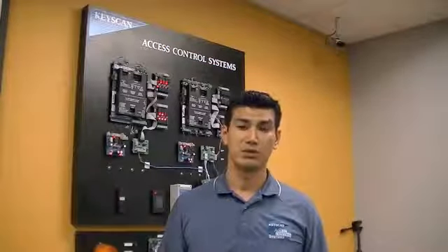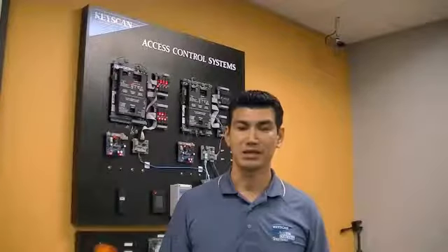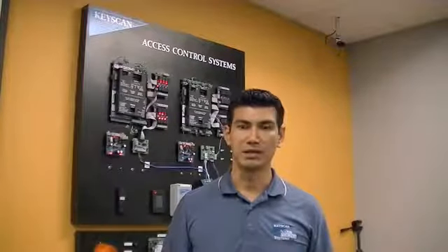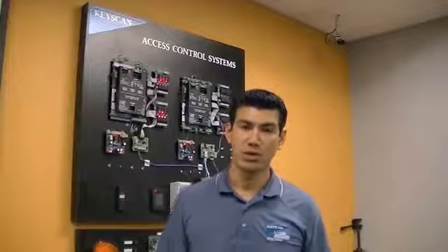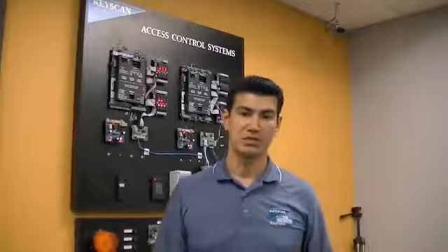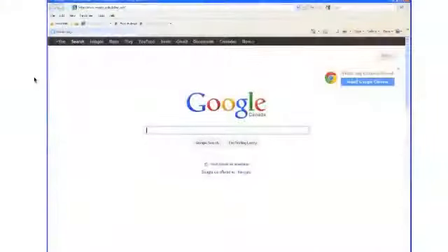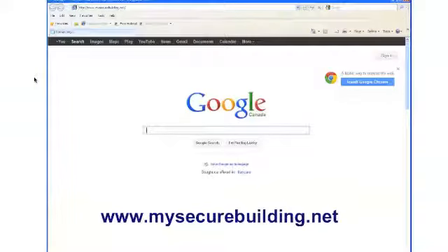Today we're going to be doing a review of the necessary steps required to get a KHS CA150 online with a Keyscan host. What we're going to be doing first to start is reviewing the login process to the terminal service to the Keyscan host, how to log in to the site, how to add the panel to the site, and finally doing a review of the CA150 wiring and connecting it to a PoE connection to establish that connection to the host.